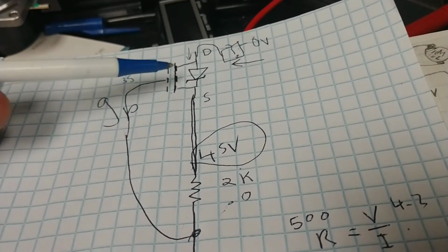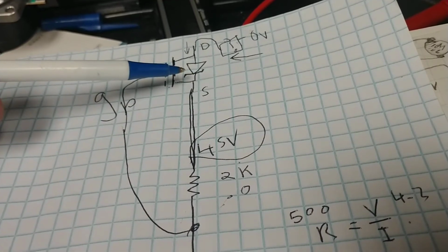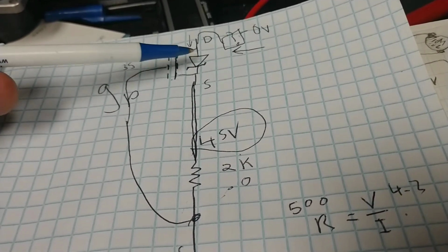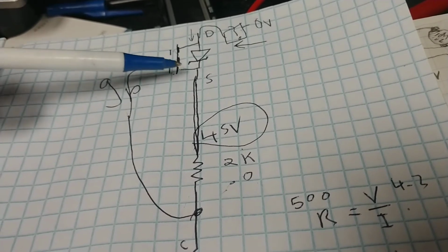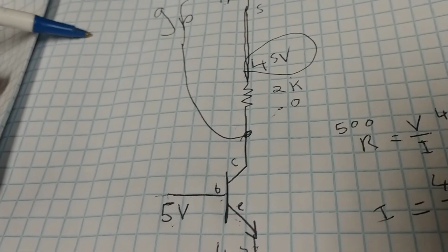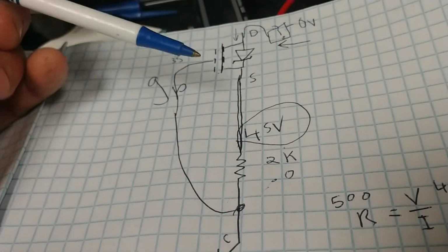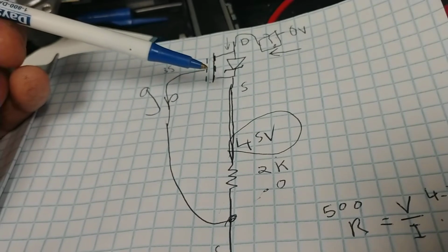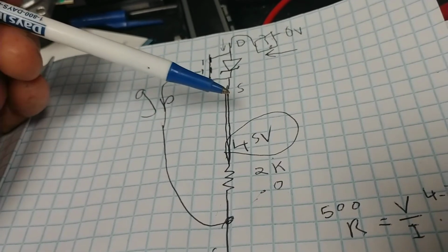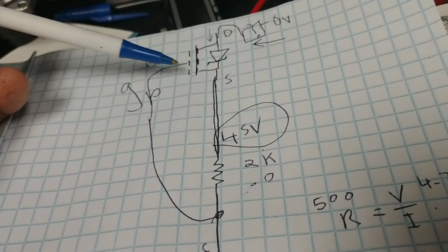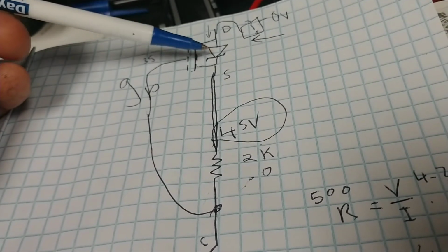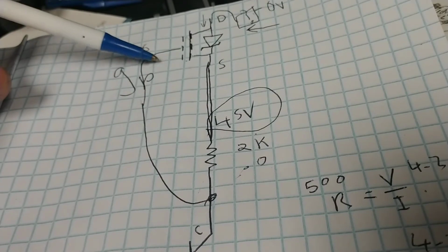But the comment is the p-type MOSFET is less conductive. If you have a given voltage, the n-type you can drive with straight up 5 volts. The p-type, you need like 10 volts, and it can go up to 20, so what the heck? It's rated to handle 20 volts, more voltage, more conductance, and that's what this thing provides.